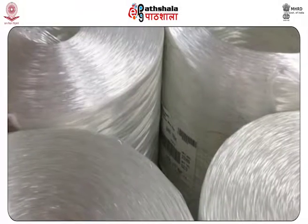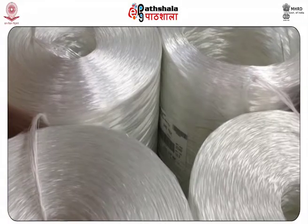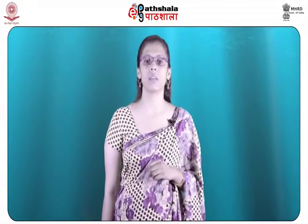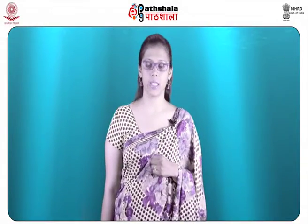Fiberglass. Fiberglass is a type of fiber reinforced plastic where the reinforcement fiber is specifically glass fiber. The glass fiber may be randomly arranged but is commonly woven into a mat. The plastic matrix may be a thermosetting plastic, most often epoxy, polyester resin or vinyl ester, or a thermoplastic. The glass fibers are made of various types of glass depending upon the fiberglass used. These glasses all contain silica or silicate with varying amounts of oxides of calcium, magnesium and sometimes boron.